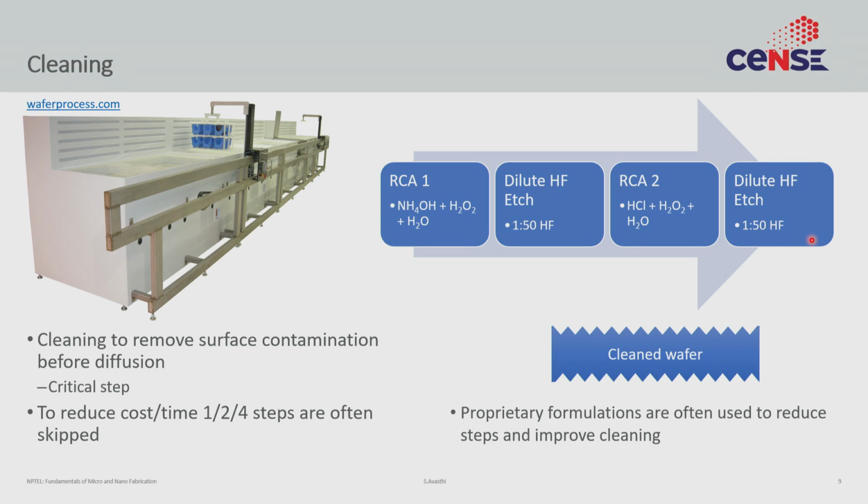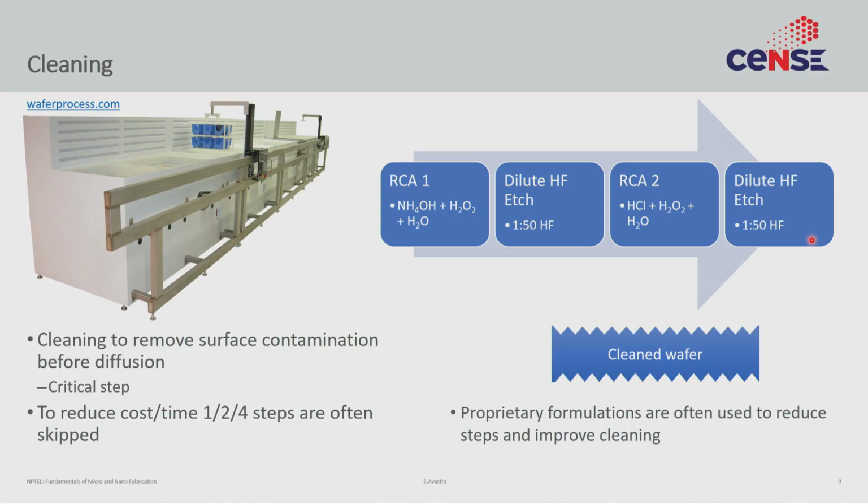Some of the research labs and really careful, really high efficiency solar cell manufacturers may still do that. The problem is this process becomes too slow. Each of these chemical baths is very expensive to make. Because of the H2O2, the chemical will not last for a very long time, so you have to keep replacing it for a whole host of reasons.